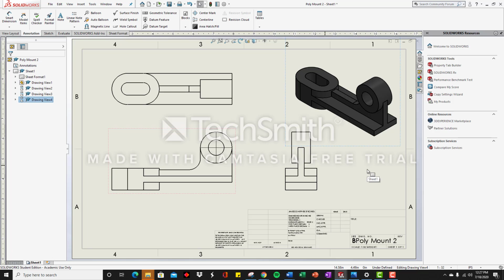we're going to start dimensioning. And dimensioning is important because it allows the engineer or engineer technologist to base off the part, or to make the part based off of dimensions and design on the sheet. So the first step that we're going to be doing is using the center line tool right up here and the center mark tool. And all these tools are located on the annotation tab.